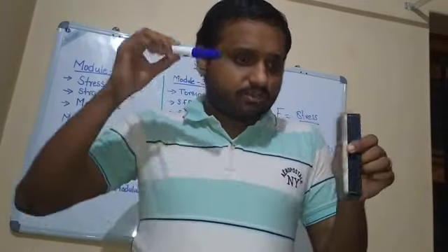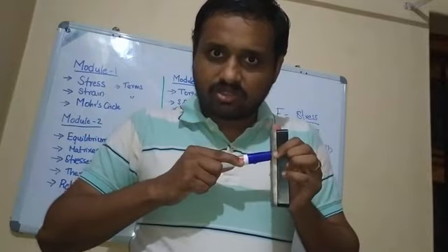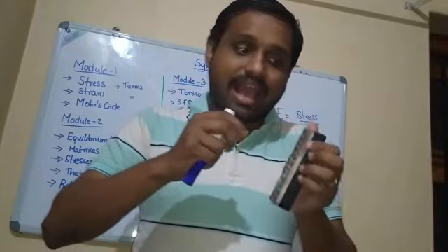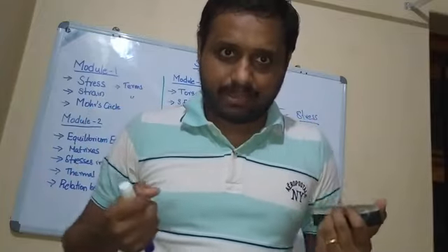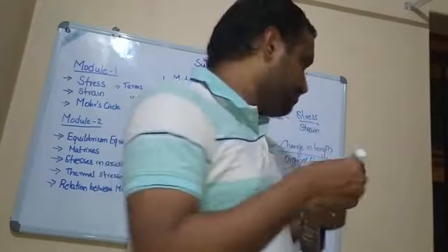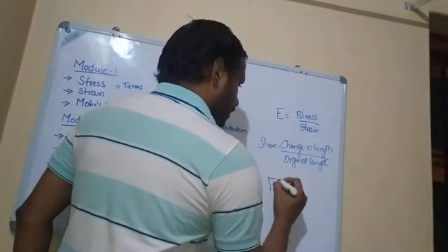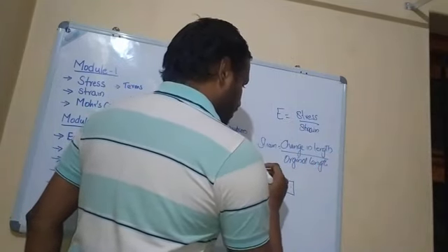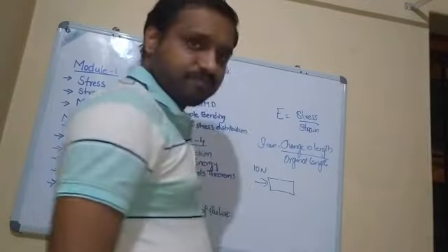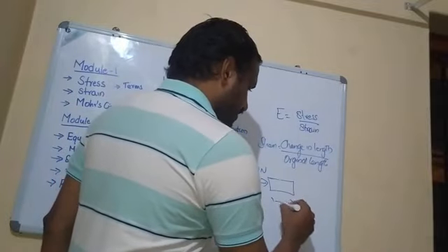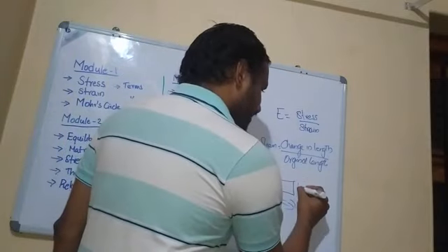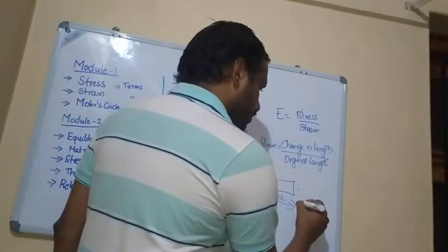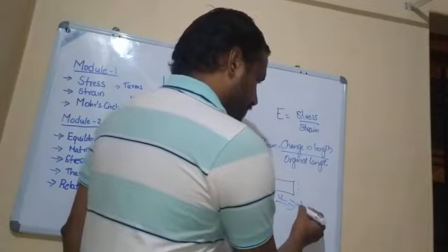So what happens if you apply some force? There will be stresses induced, as well as some deformation, and elongation can happen. Initially, say a bar is applied with a force of 10 Newton, and its initial length is 12 mm. This has increased its length by 1 mm.